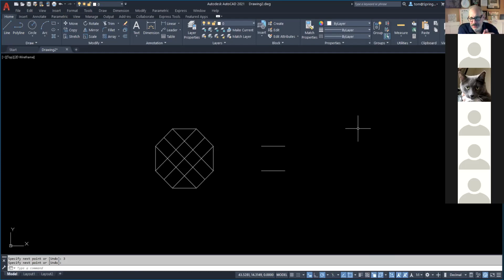And you could do the same thing with a lot of other things too here. Like let's say I want to draw a circle. If I go here to my circle command, I could go circle center radius, go ahead and go here. And I can go ahead and touch it here and pull that up. And it says how far you want it up. I'll go ahead and say 4. And then how big do I want it? I'll go ahead and say 0.5 like that. So you can space your content very precisely too.